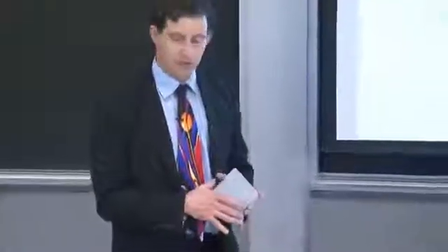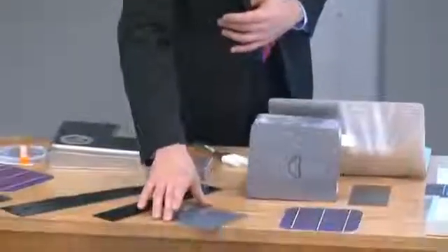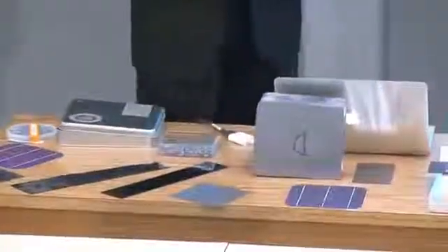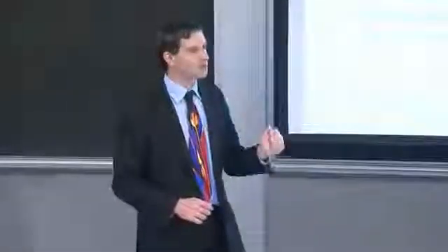This is because the solar cell has to compete against bulk power. That's its competition coming out of the wall right over there. So the solar cell has to be able to be produced much more cheaply. And as a result, typically thinner wafers are used and less expensive starting materials and faster growth methods, resulting in more defect-rich materials. So one group decided, gee, the embedded cost in the wafer is just so large. It's just so large that we have to make it thinner.